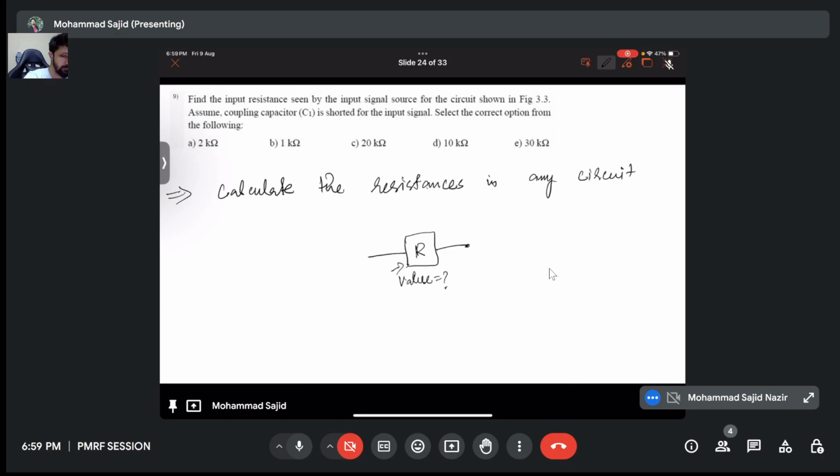What you can do is, if you have an ammeter and a voltmeter, you connect these here. You have a battery, you know the voltage, and now you calculate the current. So you connect the supplies like this, and now you know the value of V and I, so you can directly use Ohm's law and write V is equivalent to IR.